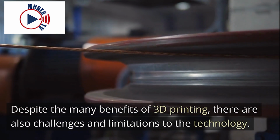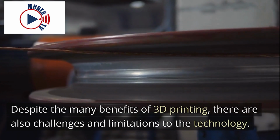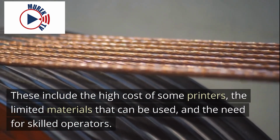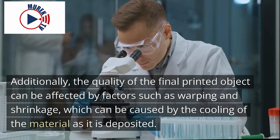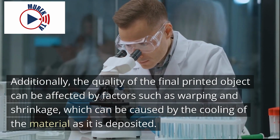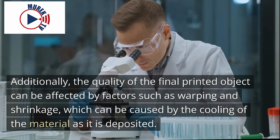Despite the many benefits of 3D printing, there are also challenges and limitations to the technology. These include the high cost of some printers, the limited materials that can be used, and the need for skilled operators. Additionally, the quality of the final printed object can be affected by factors such as warping and shrinkage, which can be caused by the cooling of the material as it is deposited.